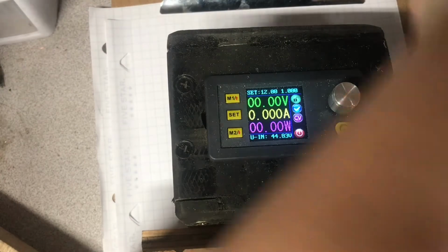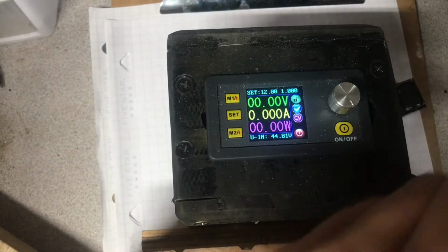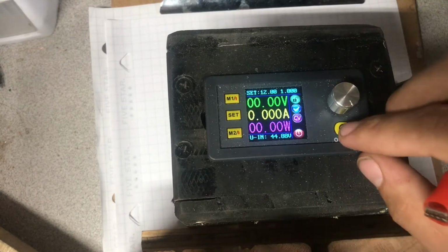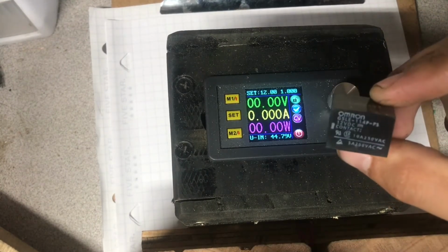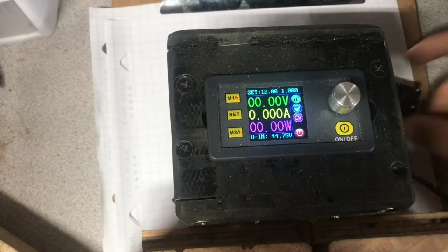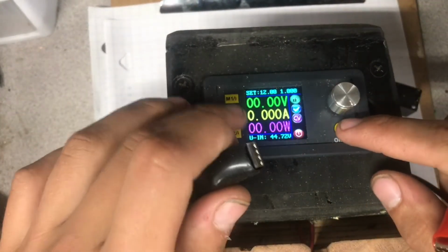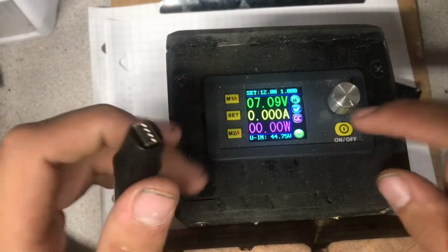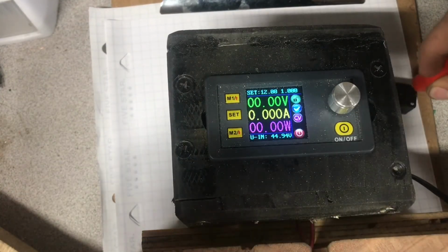Here's a relay. This tiny little guy here, an Omron relay, fairly standard part, right? So this coil voltage, especially with relays, you want to know what its coil voltage is, and that's it right there, 12 VDC. So that means 12 volts DC is what its coil voltage is. This power supply is already set for that. So let's turn that off, and then we can connect this to the coil.